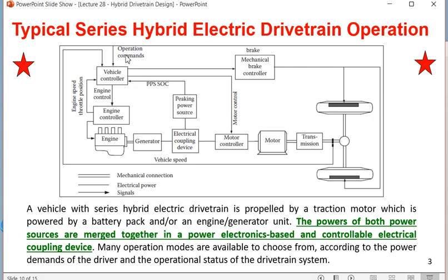So these 3 are coming to the vehicle controller. This is the main microcontroller, or the main part of the ECU, and this controller is connected with all the sub controllers you are finding. So the vehicle controller is connected to the mechanical brake controller. This is another slave kind of microcontroller. You are finding that this is connected to wheel 1, this is connected to wheel 2. All this brake related sensing, anti-lock braking system and other things are connected here. They are connected to mechanical braking, and they are taking the brake related signal to the vehicle controller. The vehicle controller should come to know everything, all the parameters of the vehicle. So this is the vehicle controller, and this is the braking mechanism control.